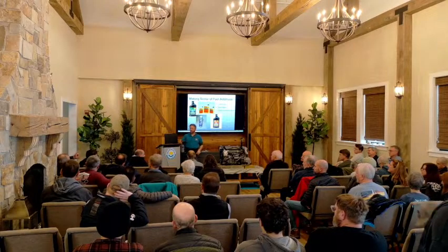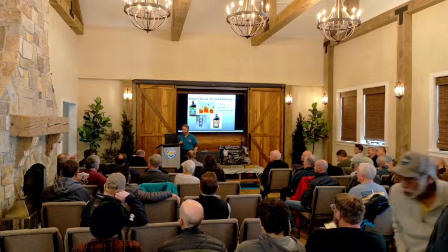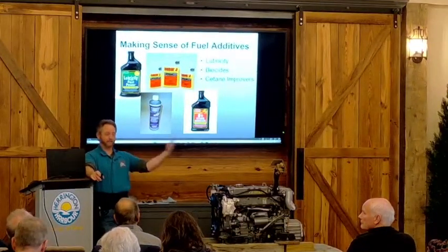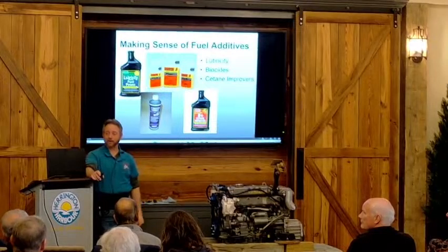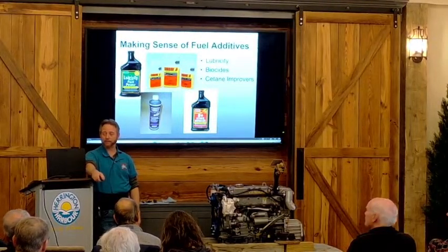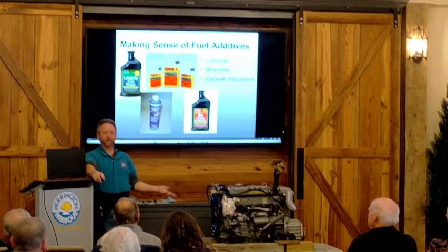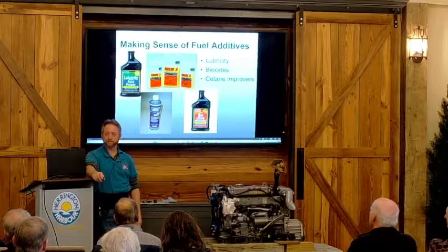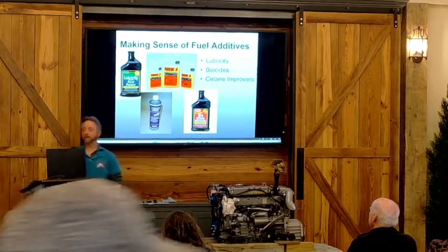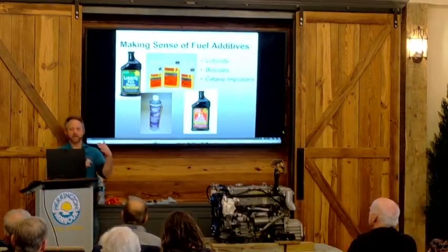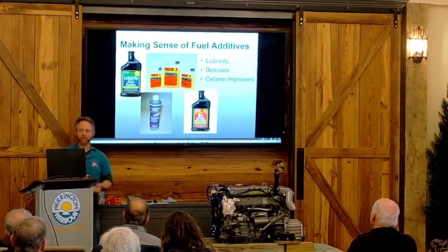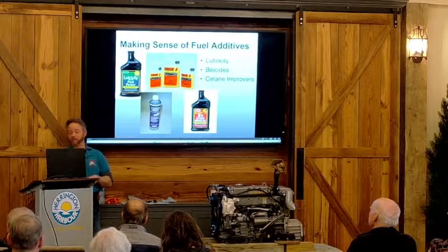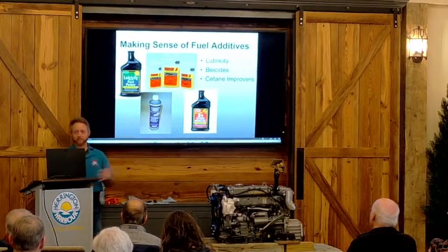So you look at all the primary filter, what about the secondary? Okay, the secondary filter, OEM filter. You're buying the micron rating that the manufacturer wants it filtered down to, and they don't really tell you. It's going to be somewhere between a 2 and a 7 micron. The frequency? If you go by the maintenance schedule, it's going to tell you every 200, 250 hours of running time. It may also say once a year.